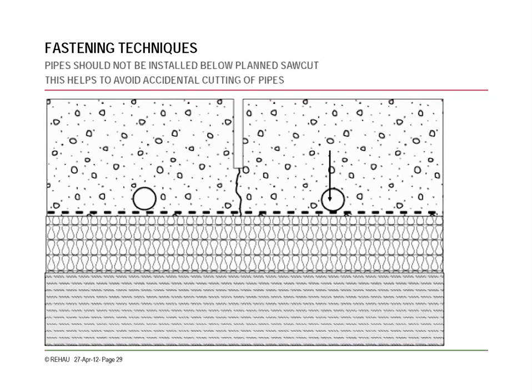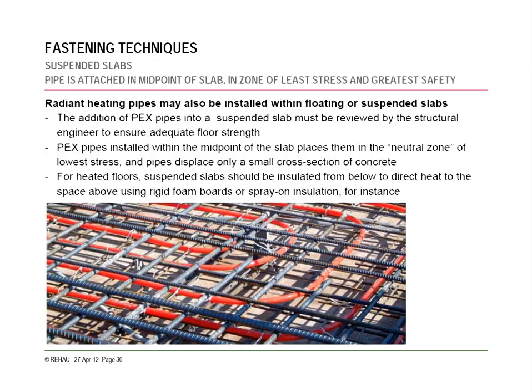Again, on the same note, if you know you're going to be planning a saw cut, or if another contractor is going to be drilling in a certain area, mark all that out ahead of time and plan your piping accordingly.